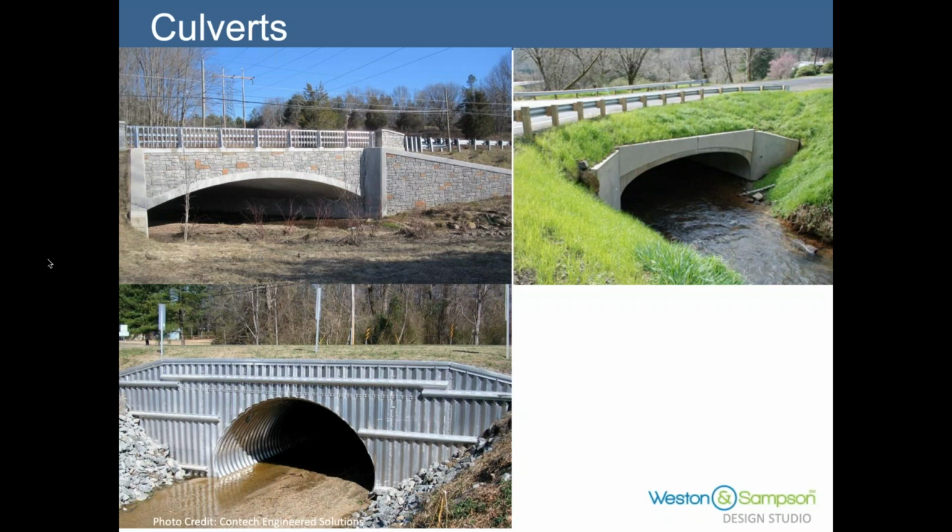There are many suppliers of these systems throughout the country, but these are useful if you're potentially having to take highway traffic over the top. And all of these examples are designed for, if you remember, I mentioned HS20 loading. So that's a 32,000, 40,000 pound design loading going over the top of the structure.